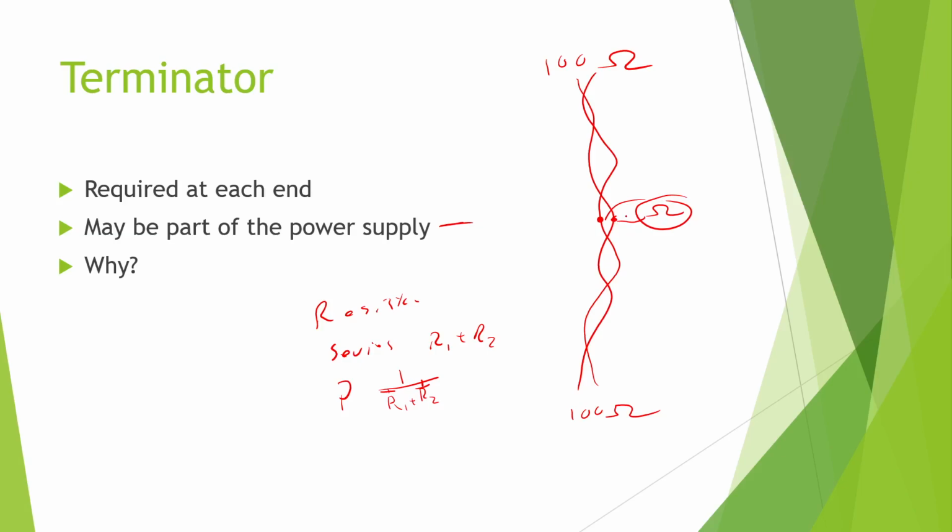So could we do this in series? Yeah. If we were to cut this wire or unscrew it from the one resistor, you could put your leads there. We cut the wires, unscrewed it, we had the other one there, then we would see 200. But the benefit of doing it in parallel is you just go to any device where you've got screw terminals, and you just poke your leads on, and you're done. So that's why the parallel option is going to be the better one.